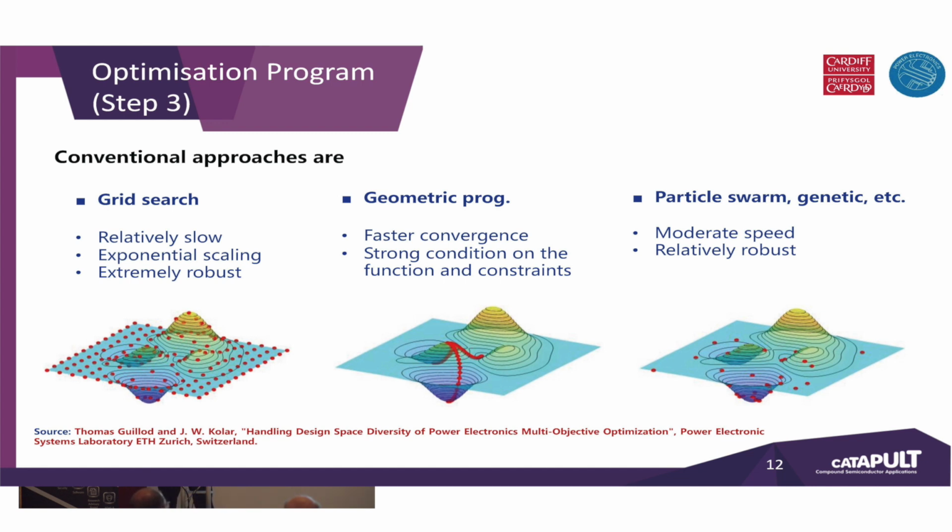which means that we go through all the points, all the mission profiles, and then calculate the efficiency, the power density, the reliability, for example, and then make a decision. So, for example, how big the inductor or how big the capacitor should be. But that is very time consuming. We actually made a calculation for a grid-tied inverter before, and we found that if we do this, it's going to take several months, considering a yearly mission profile. So that's definitely not acceptable.